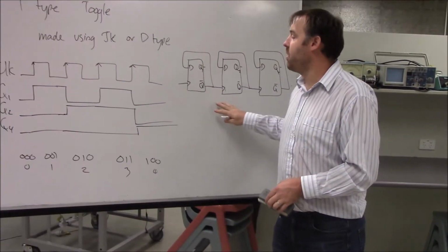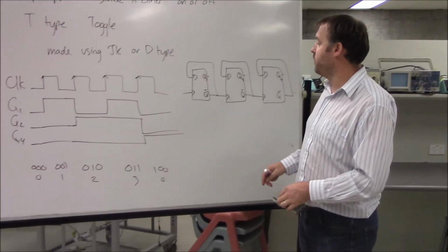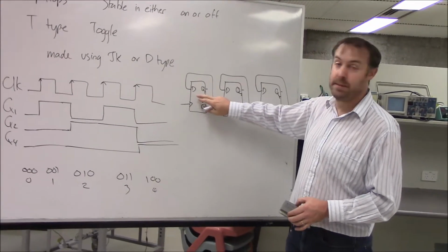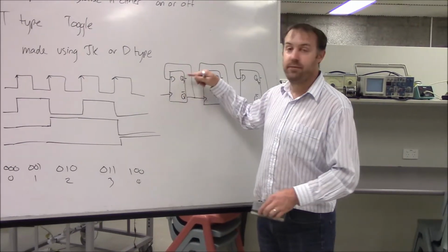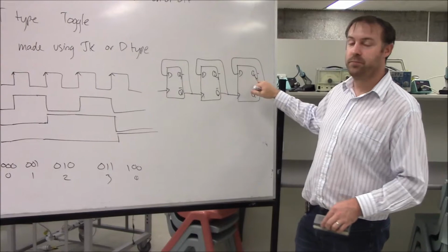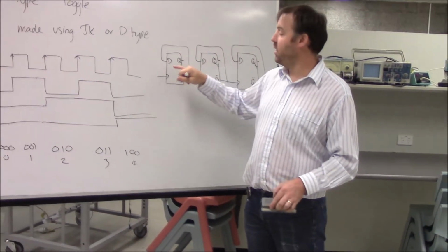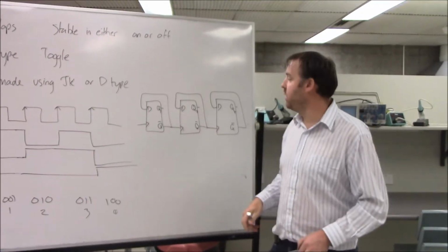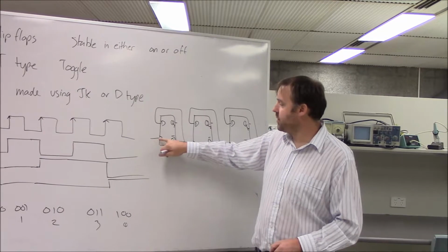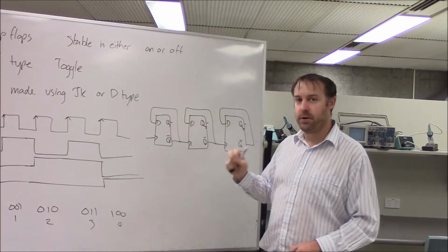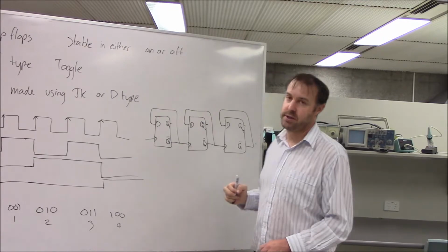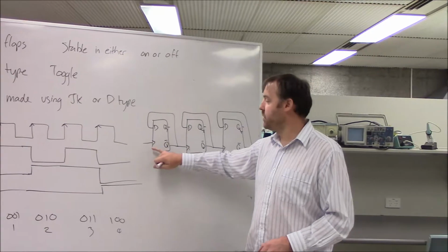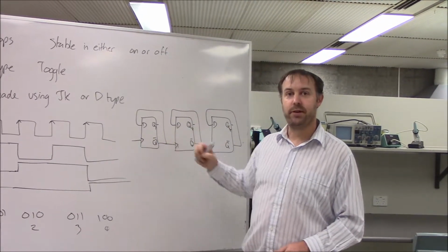Okay, so this type of counter is called a ripple counter. And you can think about what's happening here is that the changes here, as this one clocks, make this one change. It's an up counter, so at the maximum count, we've got 1, 1, 1, which is 7. And then it'll count over back to 0 again. And if you think about what happens there, as this sees the rising clock edge, that causes this to change, which might happen a fraction of a second later. It's really small, but it's real. It's called a propagation delay between the input and the output. There's a delay time.